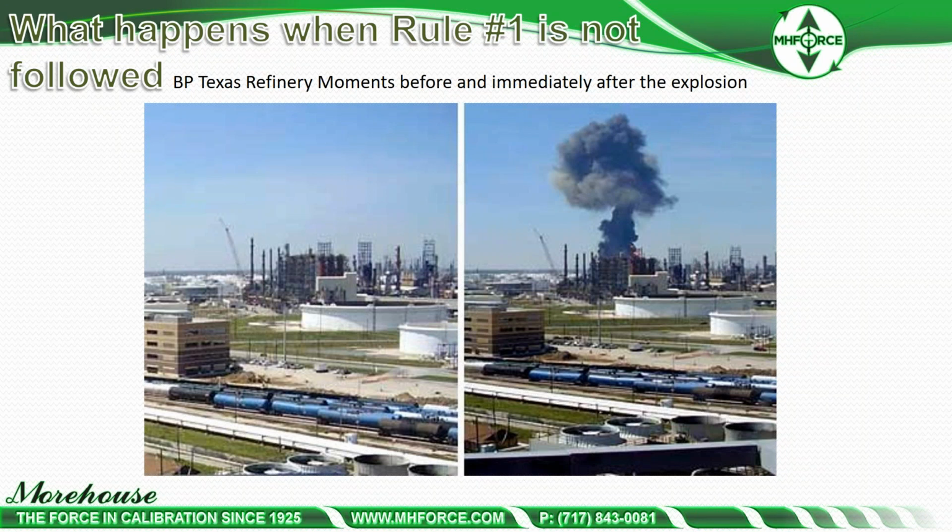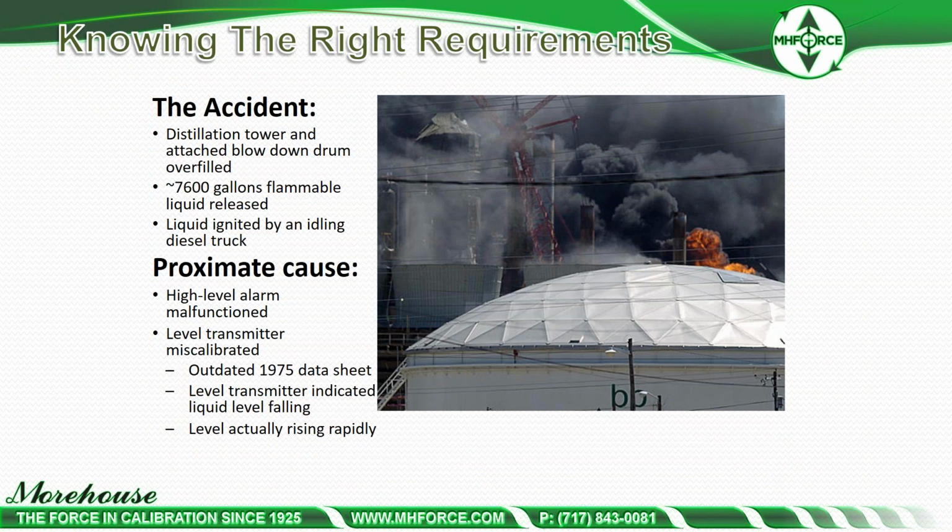So what happened? The distillation tower overfilled the blowdown drum, 7,600 gallons of flammable liquid was released, and that was ignited by an idling diesel truck.